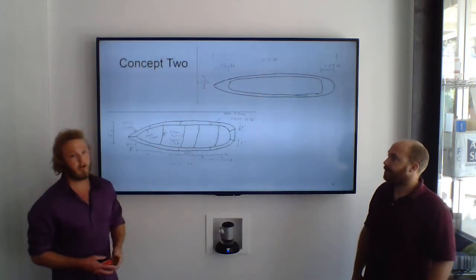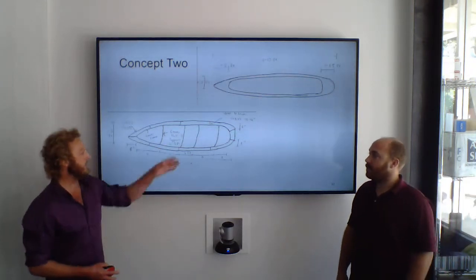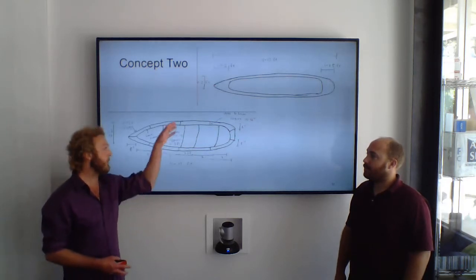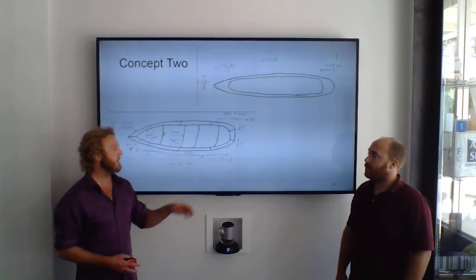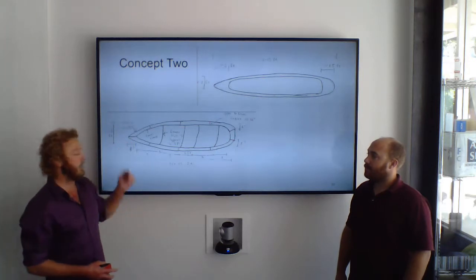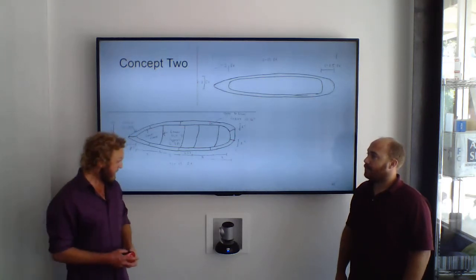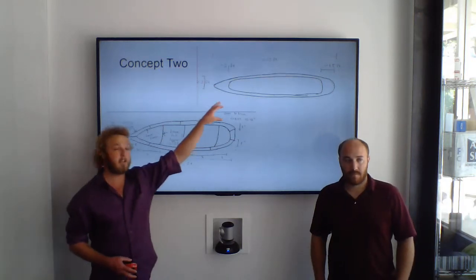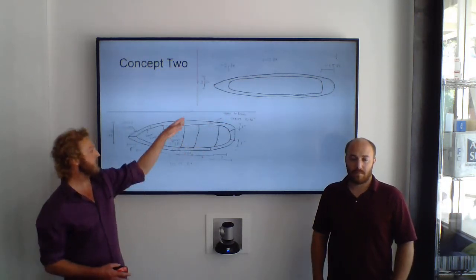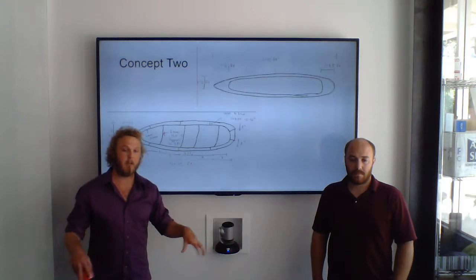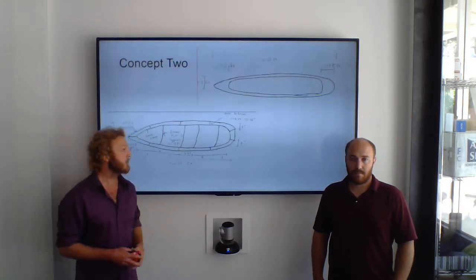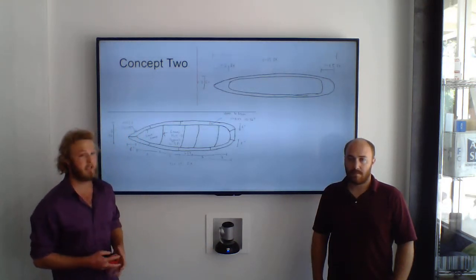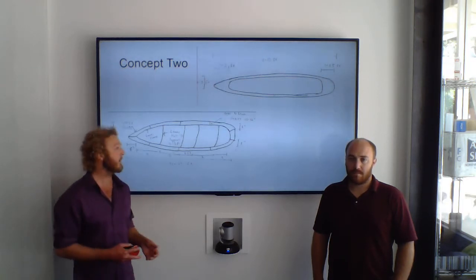And then here's the frame for this concept, which has 4 hull supports, 3 vertical supports on both sides, a wide stern, and a narrow bow. The main design here is that you can assemble the frame, put it inside your shell pocket, and then there's extension joints in the center so you can extend the frame and it will create the shell to tighten on itself and become a waterproof, usable kayak.